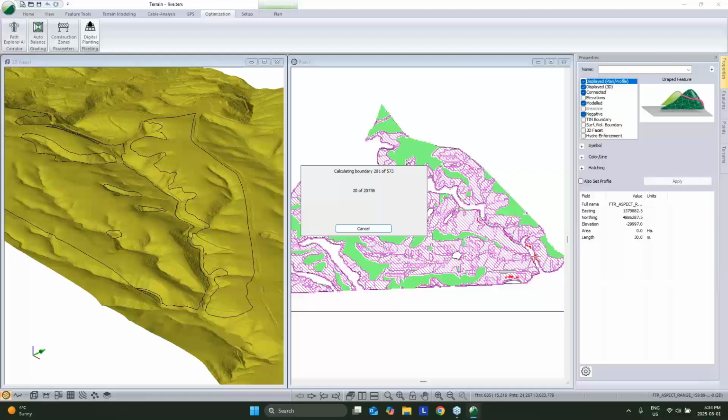Totally. How about we go both? So I'm going to just let this chug away, and I won't open a file that already exists. We'll let it do its thing. But it's just a matter of selecting your tree features, and then we can see the number of points selected after we do that. So if you want that kind of bill of materials for what to order, we can very quickly generate that.